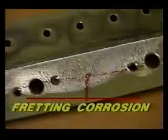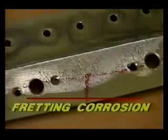Fretting occurs when two surfaces are highly loaded and vibration causes them to rub against each other. This causes their protective coatings to be worn away, exposing the unprotected metals to the environment. Fretting is often identified by black streaks at the surface interface.